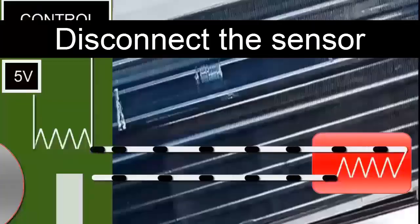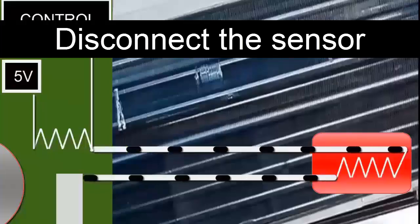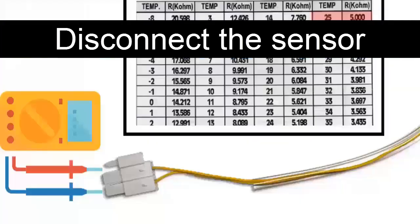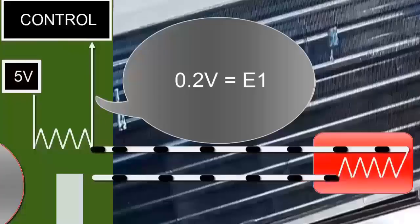E. Resistance out of range. Abnormally high or low values can lead to incorrect readings, triggering the error code. Measure the sensor resistance and compare it to the value suggested in the unit's manual. If you don't have the manual, rub the sensor with your hand and verify that the resistance decreases as the thermistor warms up.